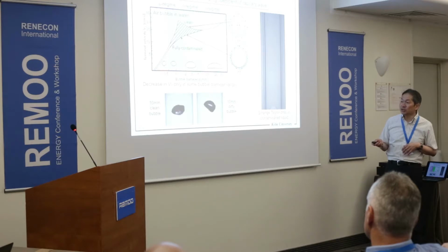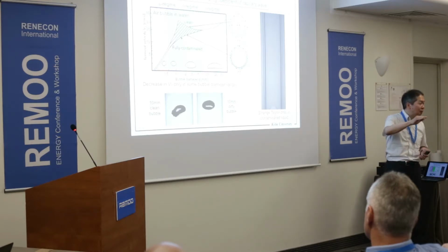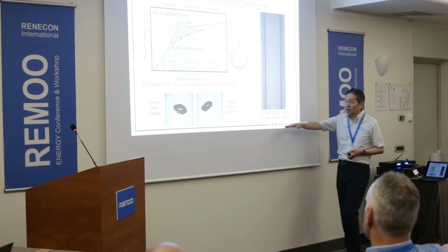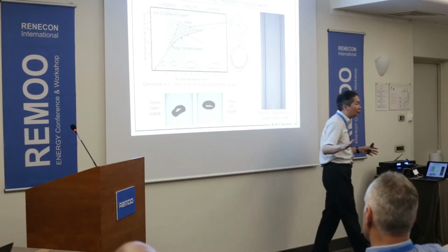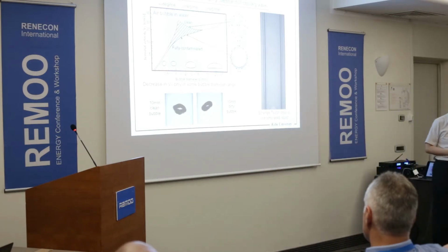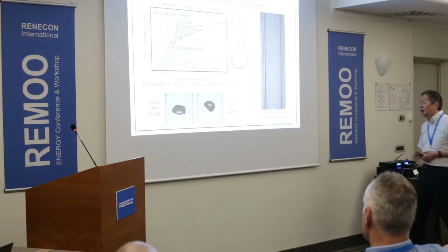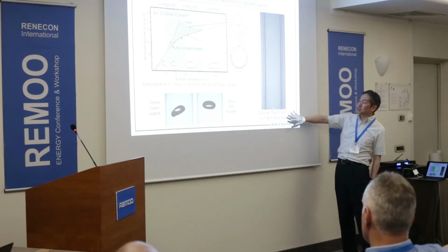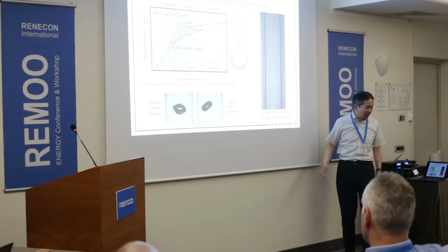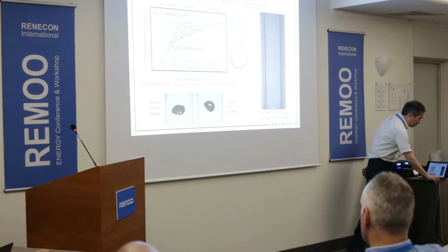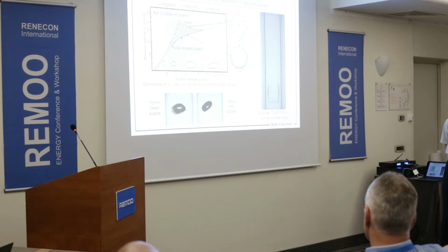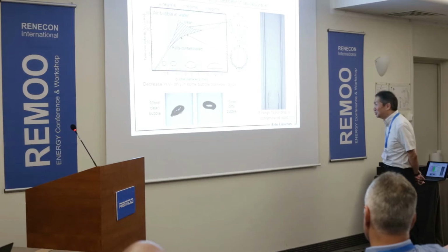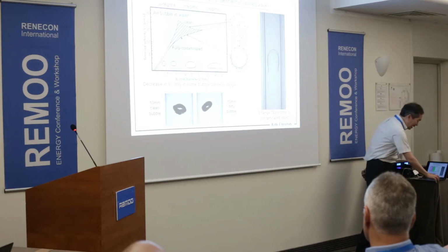As you see, in this case, we can see the small capillary wave on the bubble interface, but in the contaminated system, the capillary wave smooths out because of the high damping ratio of the capillary waves. And also, in the experiment of Taylor drops, we found very funny Taylor drop shapes because of the surfactant, like this. Very funny shape, isn't it? It's a sort of mushroom shape of Taylor drops. This is funny. So, okay.